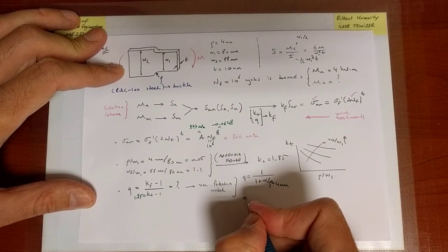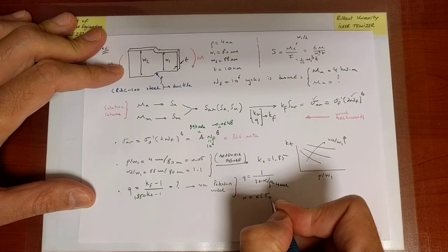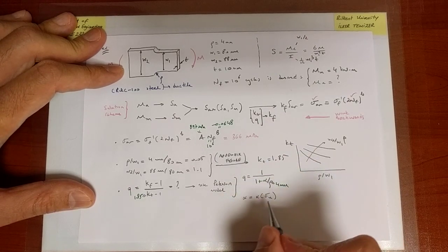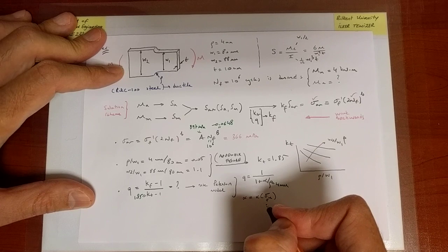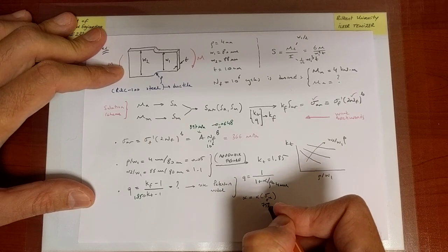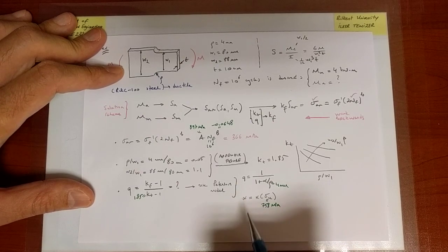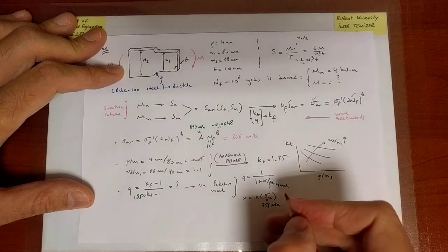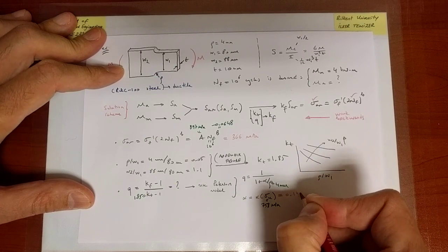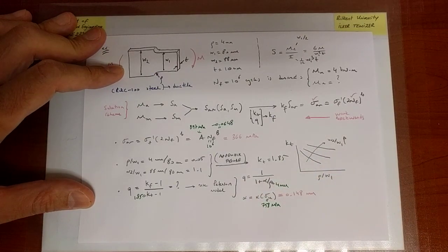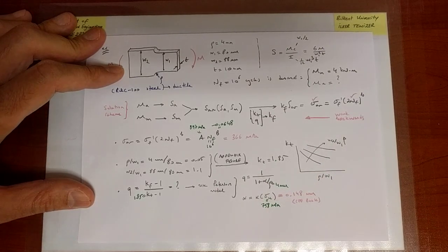In the Peterson model, there is an explicit expression for alpha as a function of sigma u, which we had written in an earlier slide. Presently, the material property is such that sigma u is 758 MPa. If you plug that into the logarithmic expression for alpha, you will find that alpha is equal to 0.148 millimeters. If you want, again, refer to the earlier slide or the equation in the book.